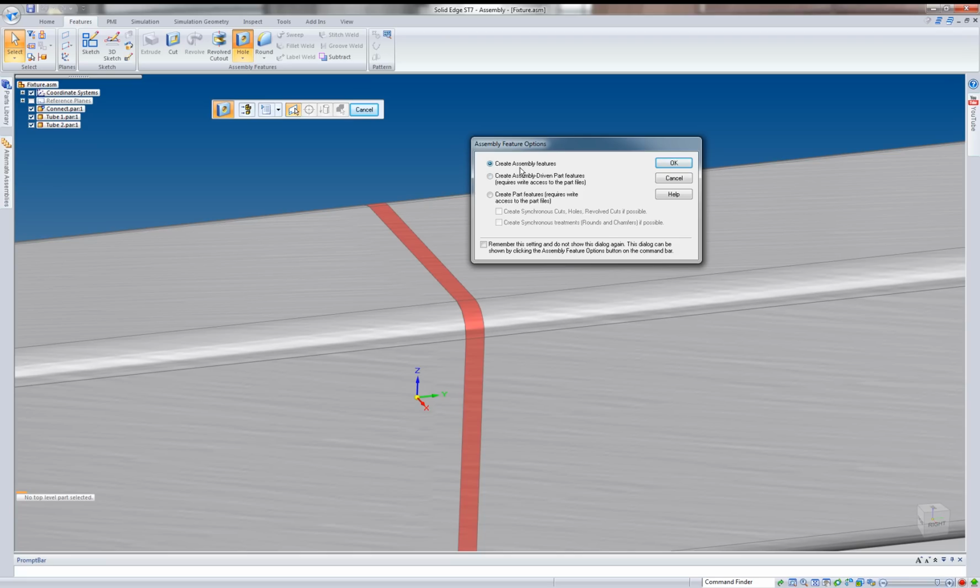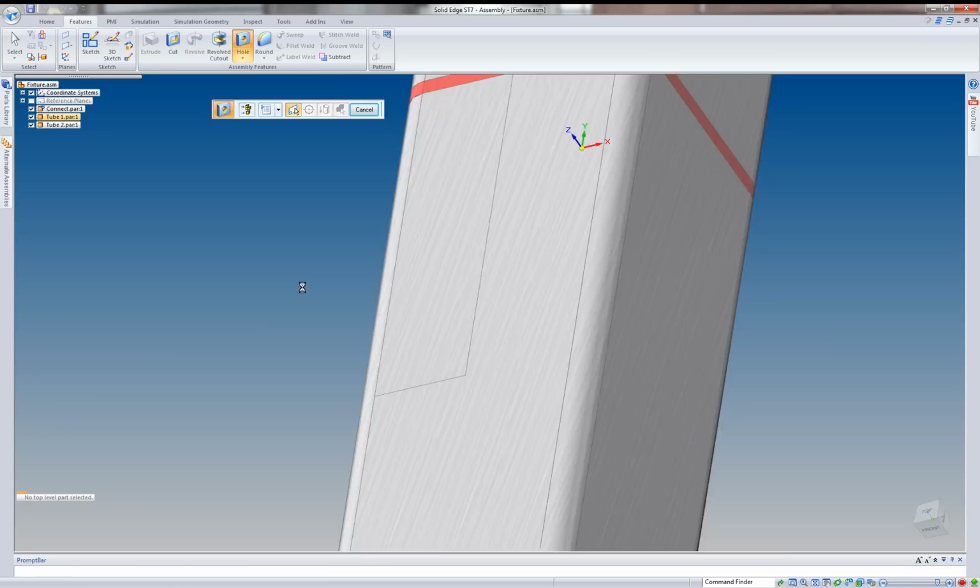An assembly feature is a feature that resides only in the assembly level. So this is like a post feature creation. After I have my parts cut and have this little bracket machined, once we put them together in the assembly, maybe they go into a jig and they both get drilled at the same time, so the holes line up perfectly. Sometimes that's kind of hard to do if you make the parts individually and create the features. So again, we'll go ahead and select that.